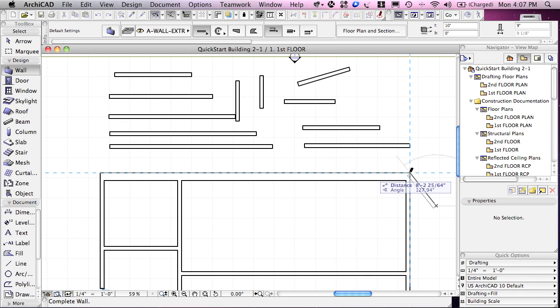Now you notice that when I point at this element here, that we have a black pencil, and that indicates that we're on the corner or the node point that we're indicating. You'll see blue guidelines shoot off in the main axis directions. These, of course, are also turned on or off by that guideline button or the Q letter. Now, if I move away from it, ArchiCAD will assume that I didn't really care about those.